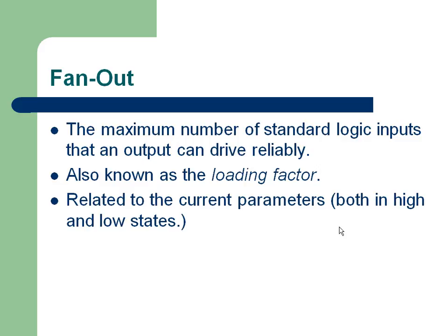The reason is very simple. In FPGAs and ASICs, the clock tree and clock lines are designed physically, in terms of metal widths and in terms of the gate sizes, source, drain and all, to deliver a larger amount of current. That is where the whole load comes in.